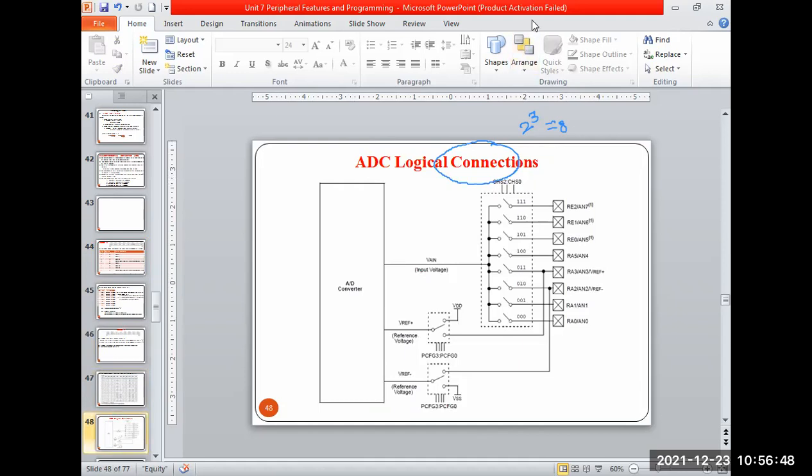So here is shown how the data is going to be converted. Okay, I'll show it here, I will use a different color. Port A, with 5 pins from port A, is used for the ADC input, and the remaining 3 pins are from port E. So port E's 3 pins are used, and a total of 8 input channels are available. I can apply the input at one of these pins, so I can say AN5. So a 5-volt signal, I am applying 0 to 5 volt by varying the port.